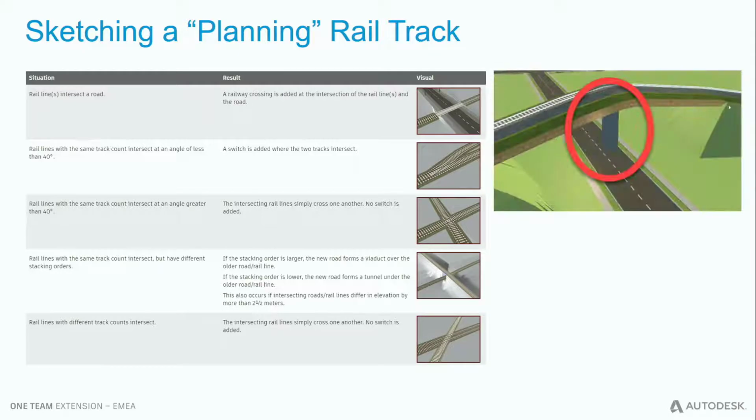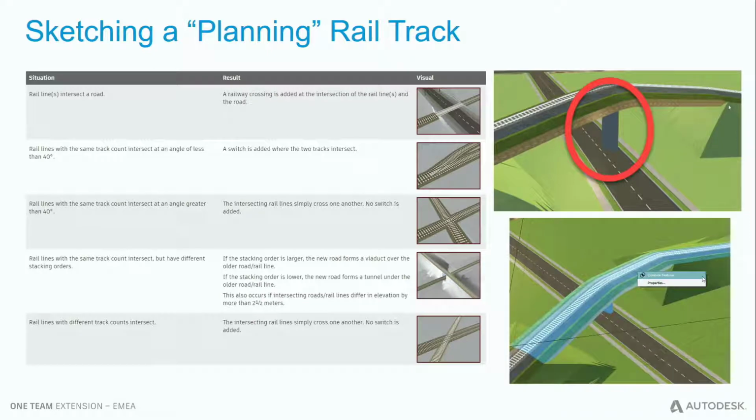The other thing that's actually limiting the power of that tool is that it has a default style in InfraWorks. If you're using, for example, the bridge style for the rail track, you will have one pillar or column supporting the bridge, but you don't have any input or power to change the location of that column, unless you make use of something we call creating a zone. So you basically split this zone and split another zone, and then you will have the capability of having the pier here, and then you will have another one here. If you're not satisfied, you can use the combine feature to connect them back again. So certain positives and negatives over there.